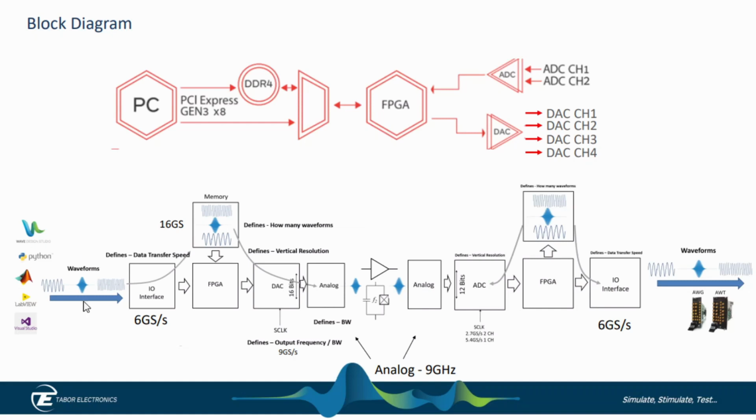So when we stream waveforms into the instrument, they're going to go straight through the interface. They're going to go into a FIFO scheme here. They do not go up to memory, and they go straight out. And this is truly a software-defined radio at this point. You could put, for example, analog audio in here, or digitized analog audio, and we could play it out. We could modulate it up to an AM or an FM band, and it could effectively be a radio station.